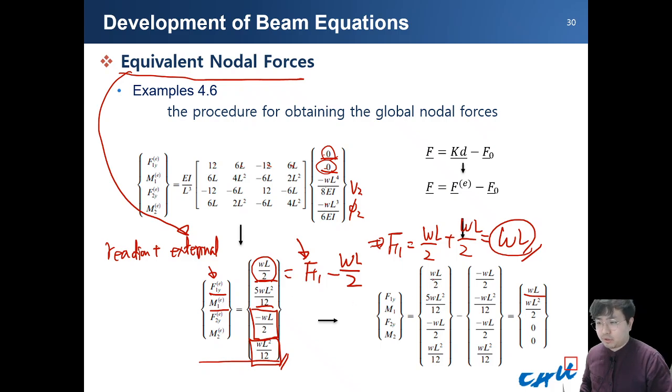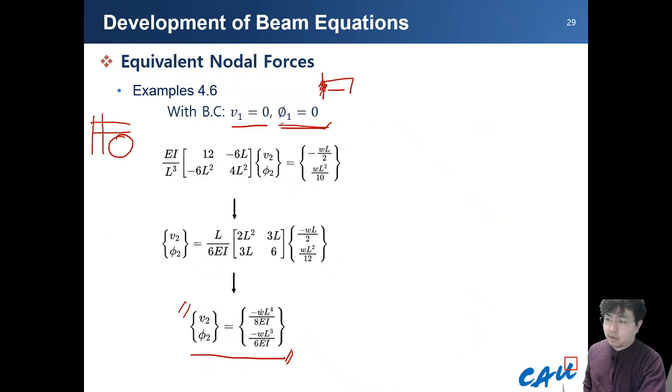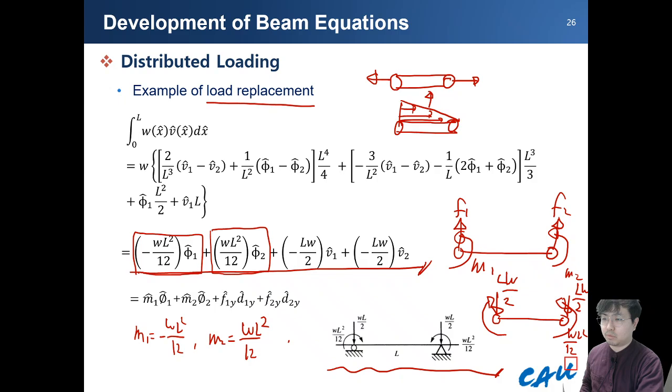That means that after obtaining the reaction or total nodal forces, you should subtract your equivalent nodal forces again, so that finally you really obtain the reaction forces or moments. So this is an explanation of this equivalent nodal part.